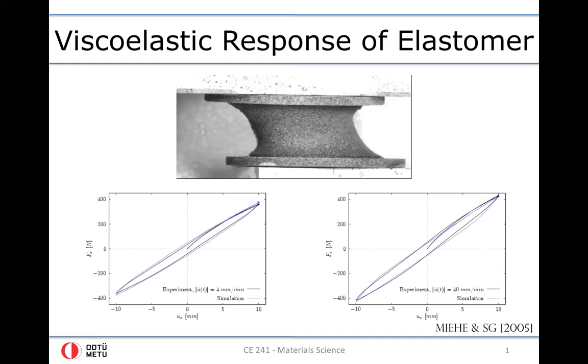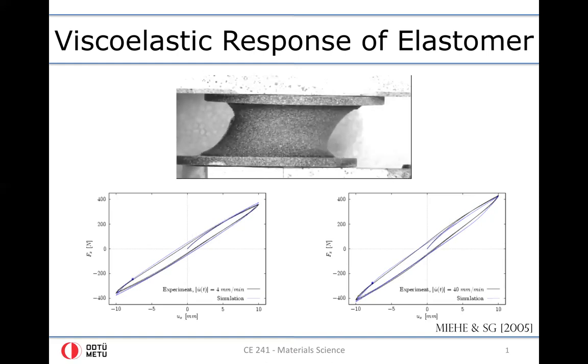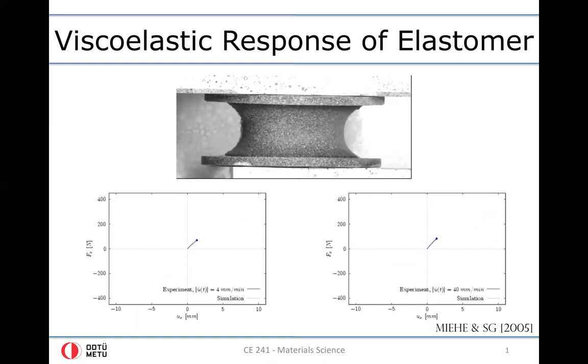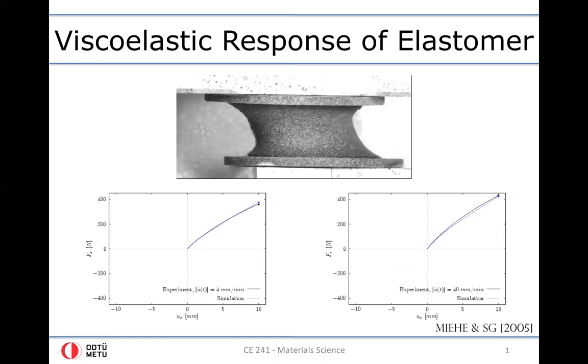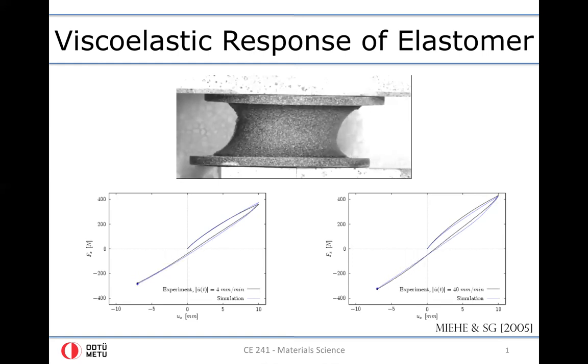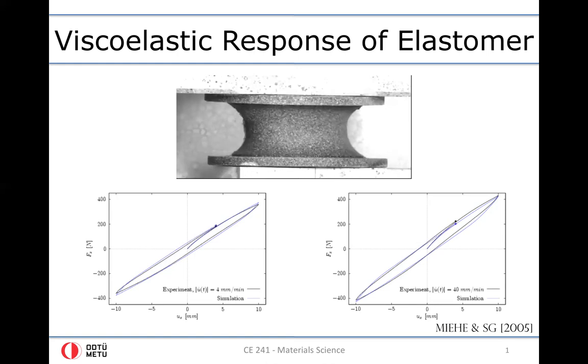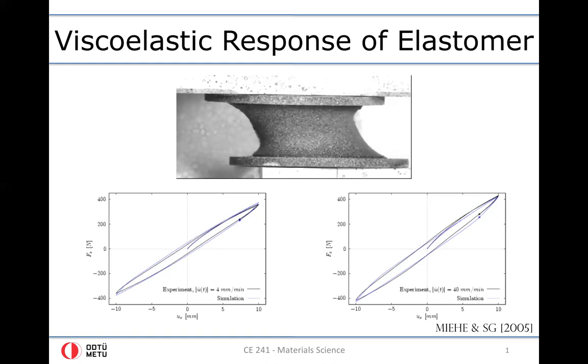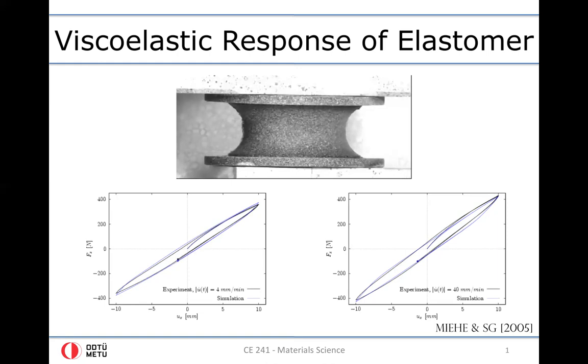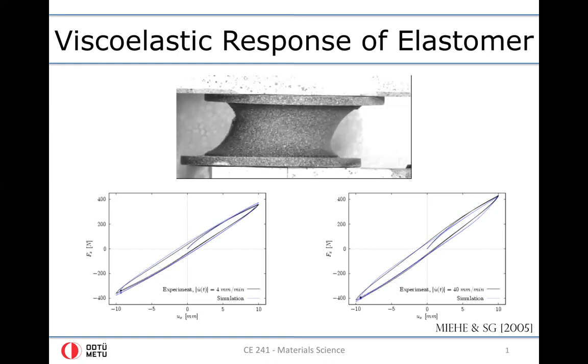Generally, there exists an optimal rate of deformation at which dissipation is maximum, and this optimum rate of deformation has a relation to the internal time scale of dynamical mechanisms taking place inside the material microstructure, for example, the relaxation times of the polymeric chains.